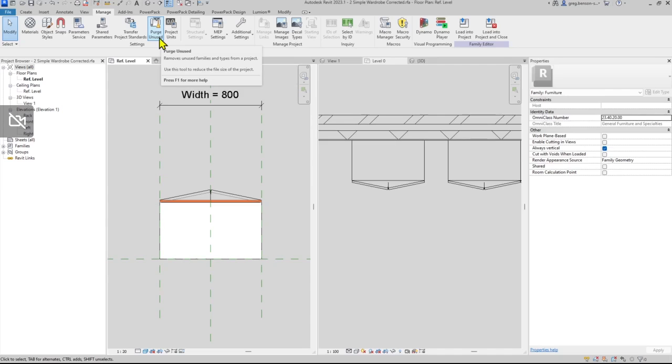General rule of thumb: when you're making various pieces of equipment, avoid modeling any internal components that you won't see in the model. All you're doing is wasting time and making a file bigger than it is. So that would include if you're bringing in geometry from other, perhaps mechanical programs such as Inventor, etc. There could be lots of components in there that you really do not need in your family because they're never going to be seen. Therefore, they're not going to be used. Okay?